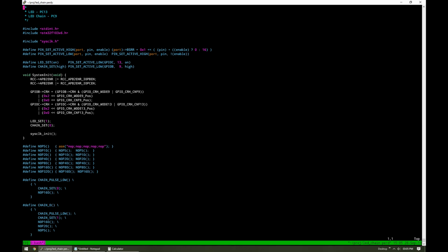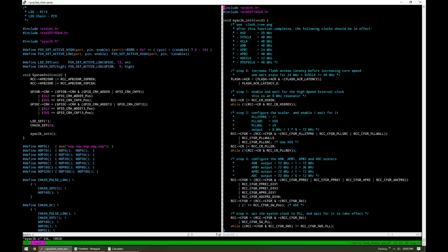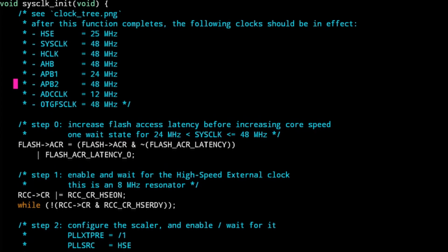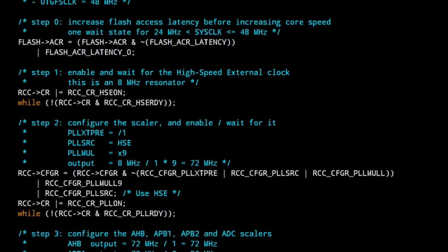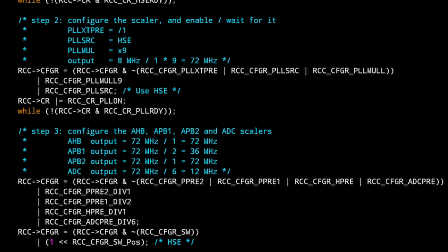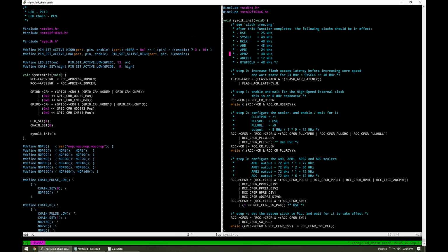I've just done a bit of work off camera. I was having some difficulties getting the timing to work out by using just NOPs, and so what I've actually done now is I've taken the system clock and configured it for the full 72 MHz, which is what this part is rated for. Clock configuration is a bit complex, so I'm not going to go into it now. But suffice to say, we can now run the core at 72 MHz instead of the previous 8, and we should be able to do a lot better in terms of timing.